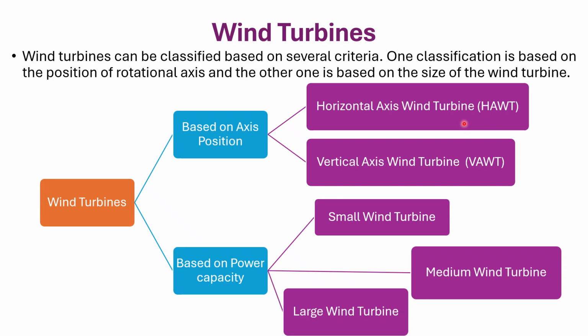There are a few disadvantages as well. They limit the utilization of the vertical design due to the design of the blades. The sweep area in this type of turbine is much smaller, and the wind speed is slow near the surface and usually turbulent.